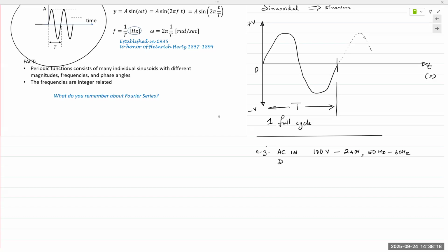And then your chargers have a DC out. Laptops more often than not run on 19 volts, and then the power adapter, depending on how much current it can supply, would be like 4 amps, 5 amps, 6, 7, 8, 9, 10 amps. My laptop is about 12, 13, nearly 15 years old. It has a brick of a power supply, about 250 watts or something. So it's 19 volts and about 10 amps of current, which is an ungodly amount. Huge.